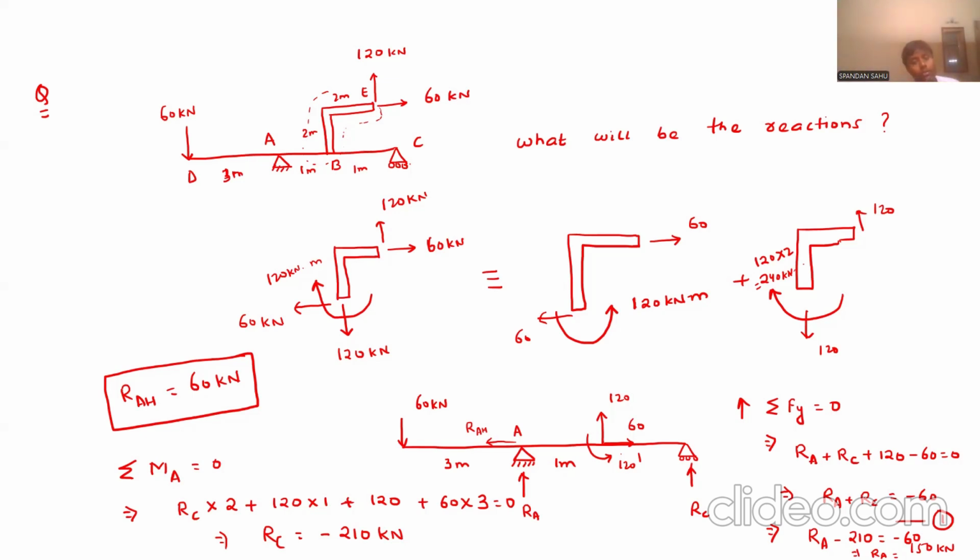After that, you just superimpose those two images to bring that to your original beam structure, and write all those reactions and moments that will complete the given structure. And then try to analyze the structure using the equations of static equilibrium respectively. And that is what we have done throughout this question.